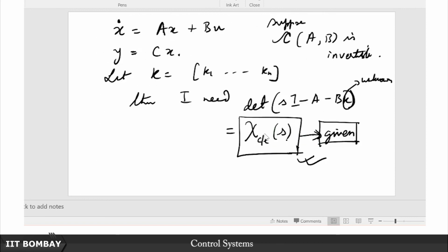Here the price you will be paying is that whatever computation you want to save in terms of computing this controllability in the phase variable canonical form, taking its inverse and all that, which might appear pretty cumbersome, at the end of the day you have to solve for n equations in n variables, and you will see that those are not necessarily decoupled.